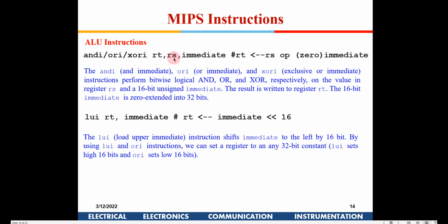Here, if you see, it is zero extended. So the 16-bit immediate data is zero extended into 32 bits. It is not sign extended. Whenever we are doing these logical operations, this is not an arithmetic operation, so zero will be extended.